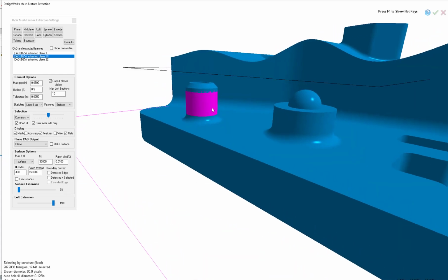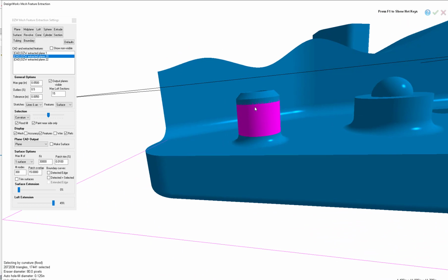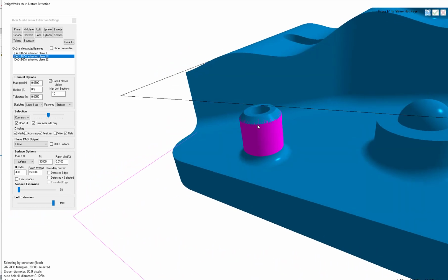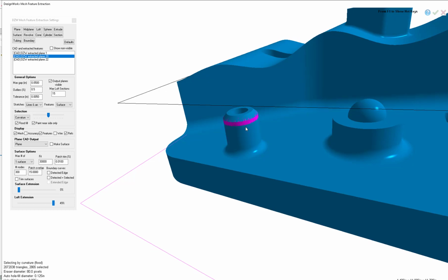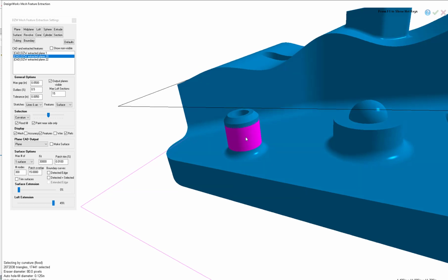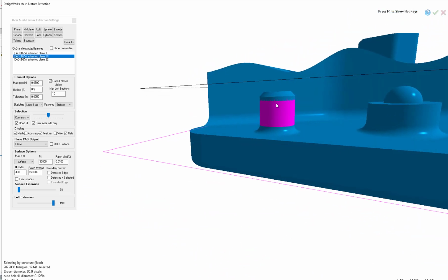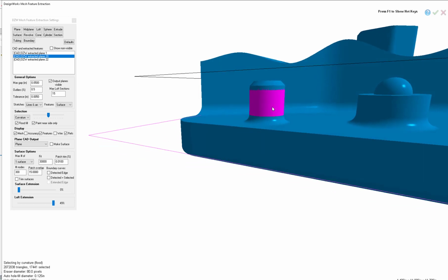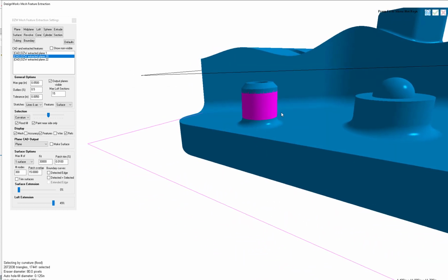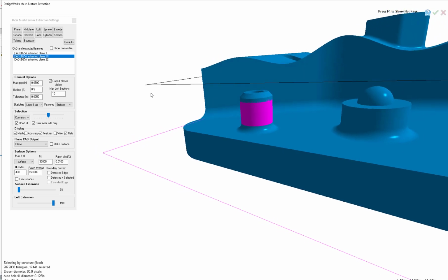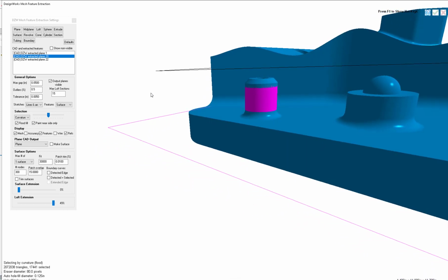And you select it. Now again, you can see what happens here. You either can paint too far. So if you painted too far, hold down the control key and click down here. Or wipe it all out, doesn't matter. Or left click again. And you'll see it's going to be short of where it should be. So none of the other products out there can identify a feature, then say go to the top and to the bottom. But DesignWorks can. So now what we can do is tell it that we want it, in this case we told it it's going to start here. Okay?